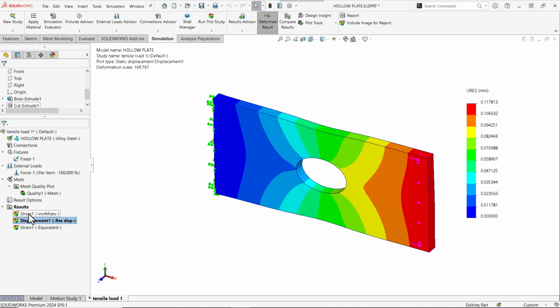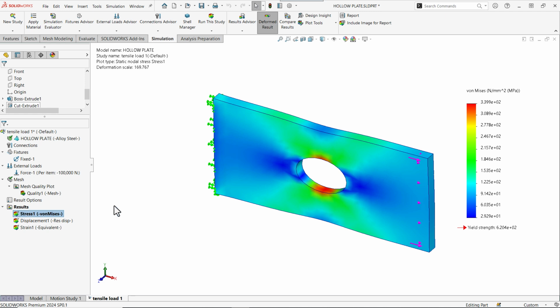Alright, in stress 1 plot, so first activated, we see von Mises stresses. And those are nodal stresses. Nodal stresses, meaning that stress results are extrapolated to nodes and then averaged on nodes among different elements. So let's do some housekeeping. We'll call this plot von Mises nodal.